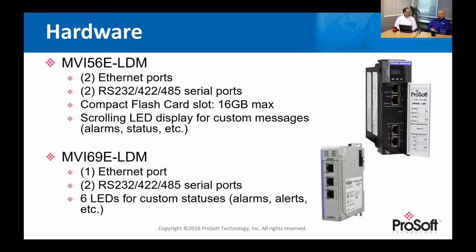Yes, absolutely. And all of these LEDs and scrolling displays are fully controllable by the programmer. So in the application, they can control the state of the LED and on the CompactLogix model, even the color of the LEDs. And on the ControlLogix module, of course, they have full access to the display to scroll whatever status messages they deem necessary. They can scroll, like anybody familiar with our modules, we scroll OK, and the IP address, and often sometimes the configuration.